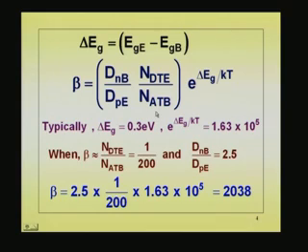Now, I just brought this in because I just wanted to point out to you the additional benefit that you get from the heterojunction bipolar transistor. You do not have to worry about the band gap narrowing effect in the emitter. Once you do not have to worry about that, you do not have to be concerned about some of the temperature dependent effects which are coming there, or beta getting lowered because of that. Now, here, these equations we have seen using some values like delta Eg 0.3 and the doping ratio as 1/200, you would expect that current gain to be about 2000. That is beta dependent only on the emitter efficiency.